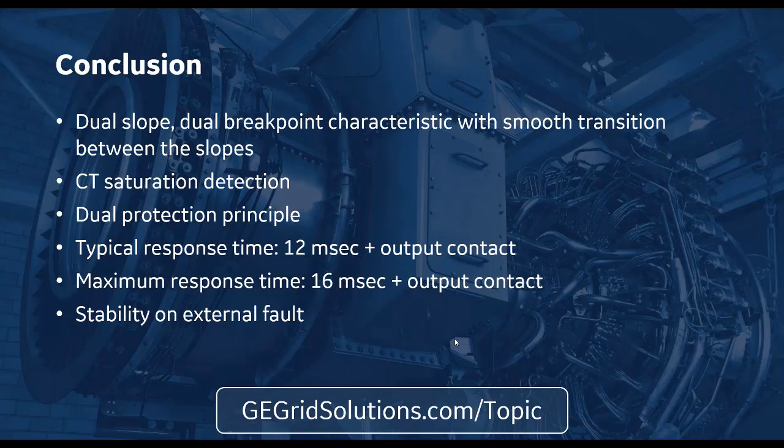And the beauty of that is these new relays, as I refer to it, can have promiscuous use of the CTs. Correct. And the beauty of this low impedance bus differential is I can actually have up to 24 different sources. So like one of the questions that came in, do I need to parallel CTs? With GE Multilin being able to have 24 separate sources, you probably can cover everything you need.